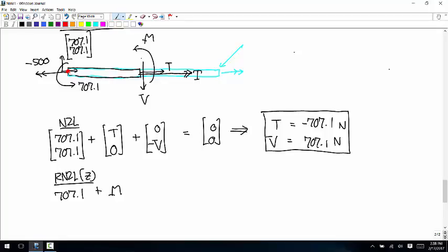Yeah, V does. And what's the moment arm for V? Yep, so we have a moment arm of 0.5 times a force V. And then if you applied that force V, say it was 50 or some positive number, would that make this thing rotate clockwise around the about point or counterclockwise? Clockwise, so that's negative.